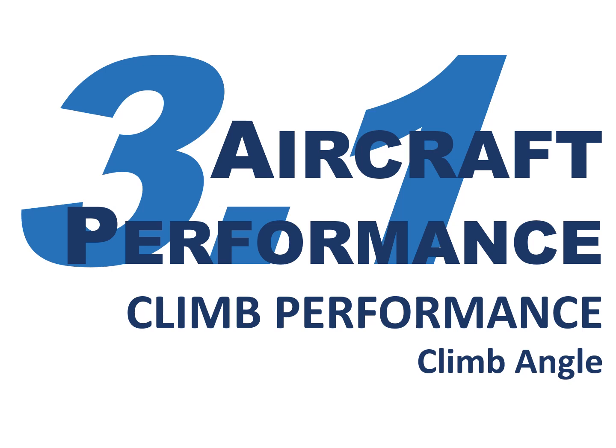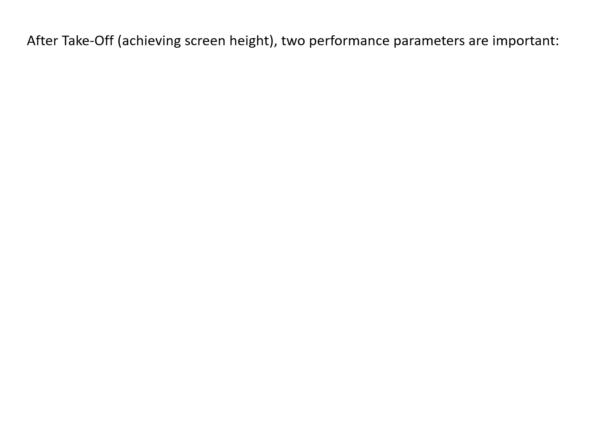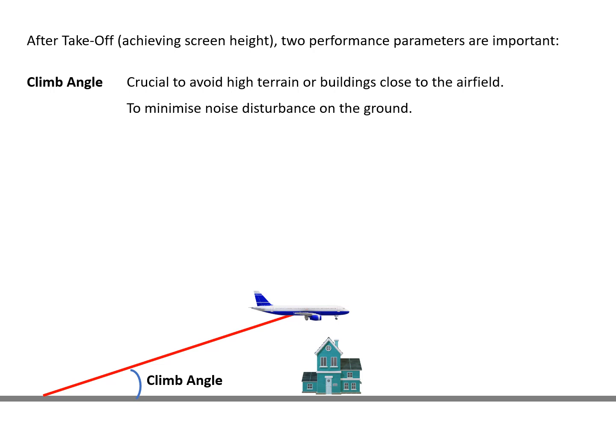In the third chapter, we will study the climb performance, and the first mini lecture is about the climb angle, or the angle of climb. Once the aircraft has achieved the screen height, which basically means when the takeoff has finished, two performance parameters need to be considered in the climb phase. The first is climb angle.